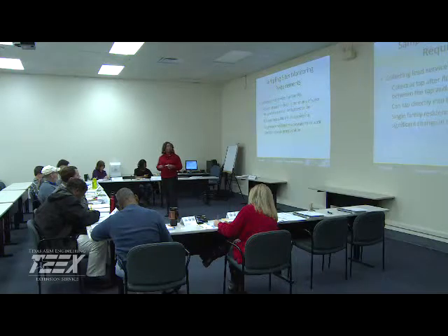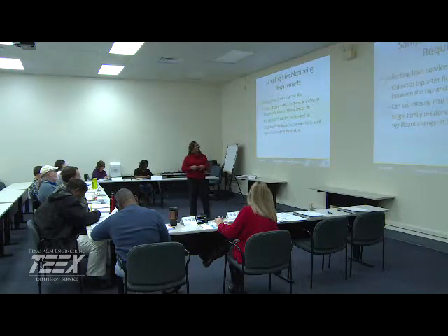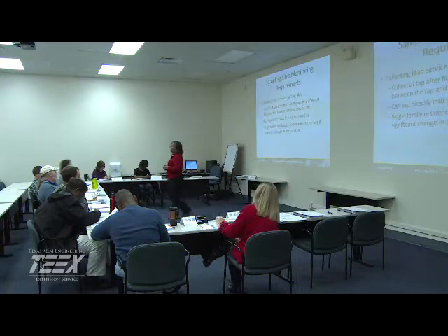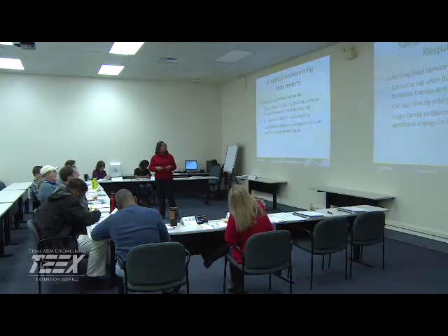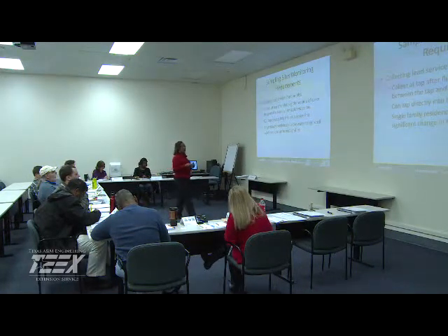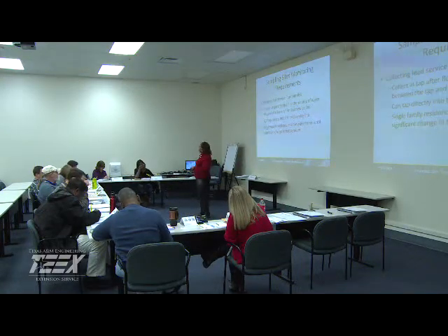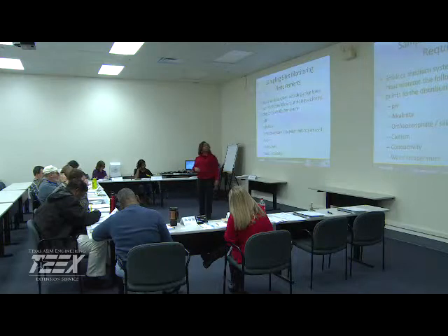Prior to collecting that sample. Or as a utility, they can tap directly into the lead service line, so you don't have to deal with residents on this one. Single-family residents allow the water to run until, again, a significant change in temperature. Now we know that we got the water coming from the main.